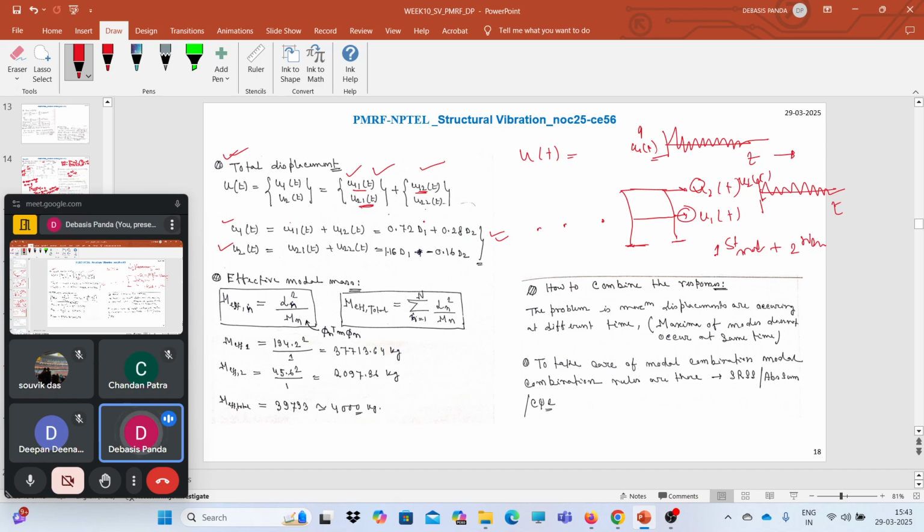Now here the problem is the peak values d1, d2. We can easily calculate it either by solving it numerically and then looking for the maximum response, or we can use the response spectrum method to find out the peak responses. We can easily find the SD value corresponding to omega and zeta, right? And if we substitute the value here, we can easily calculate the responses, right?